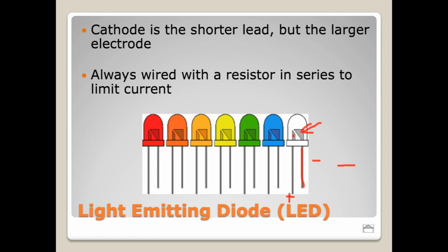This pattern down here with the legs is something that's very important to note, and we're going to see this with other polarized components. If they are in this lead configuration where they have the two leads on one surface, this is called a radial lead configuration. We'll talk more about that when we look at capacitors. If they're in a radial lead configuration and they're polarized, the longer leg is always going to be positive. Now, that's a good rule to know.